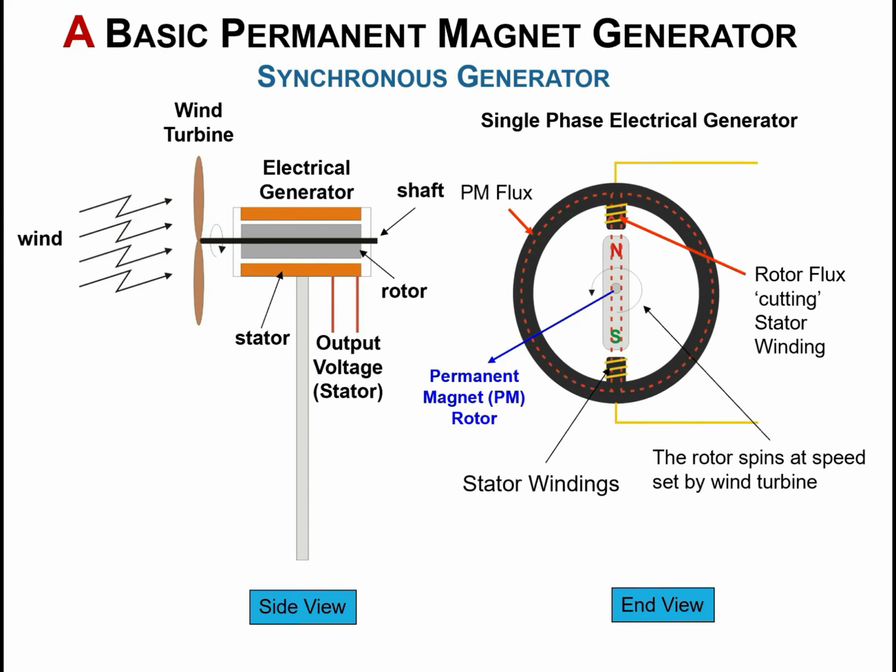In fact, there are three ways to move the rotor to produce a rotating magnetic field. By induction, as in the previous example where the generator used was asynchronous, or by permanent magnet, as we will discuss now in something called synchronous generators, or by using an external exciter, which is a small source of DC current that energizes the rotor, as we will discuss later on.